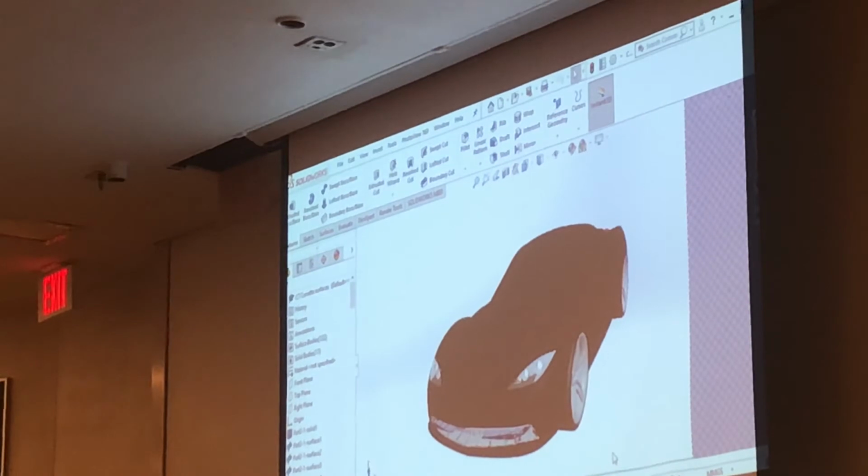Okay, so rendering in general is just a term that refers to producing a two-dimensional image of a three-dimensional object. And there are two popular ways of doing rendering. This also usually shows up on the next lab exam as a short answer question in one form or another. One way is called rasterizing. With rasterizing, we're simply taking this three-dimensional object and geometrically projecting it onto a viewing plane. And that's what you're used to looking at in your SolidWorks models, as a rasterized image.